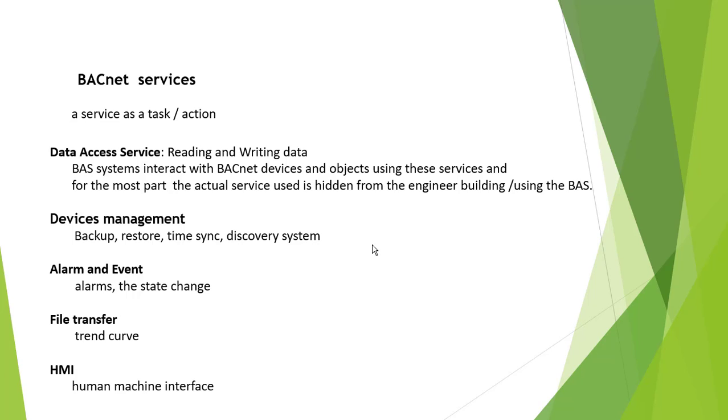BACnet service is just an action. A service is a task or an action. It includes data access service. Data access service means reading and writing data. Device management covers backup, restore, time synchronization, and alarm and event, for example, alarm and state change. File transfer is the trend curve. HMI is human machine interface.